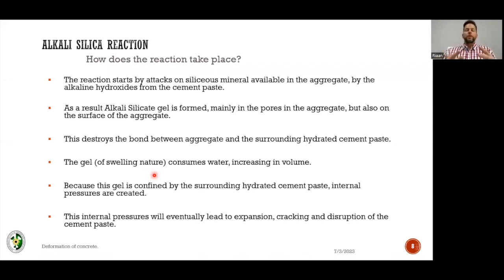Now, as soon as the cracks are there, water gets in even more readily. So every time it rains or every time there's precipitation in some form, shape, or way, even in an area with high humidity, you have moisture getting into your concrete, getting in here where this gel wants to grow. And that is not a good thing.